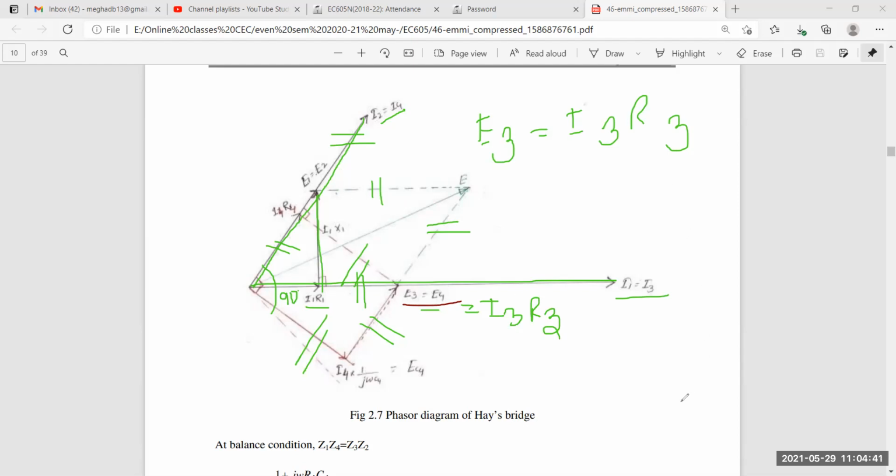Okay, so you see here the current passes through the arm AB. So you visualize the diagram which I showed you, AB. Current through AB, they have a potential drop of I1 R1, right? Which is the same phase as I1. Again, the total voltage drop across AB is determined by adding the voltages I1 R1 and omega I1 L1. Okay, so I told you because the frequency has been taken here. Again, the voltage drop across the arms AB and AD are equal, which I told you. In the first thing I told you that AB and AD have equal potential drop.